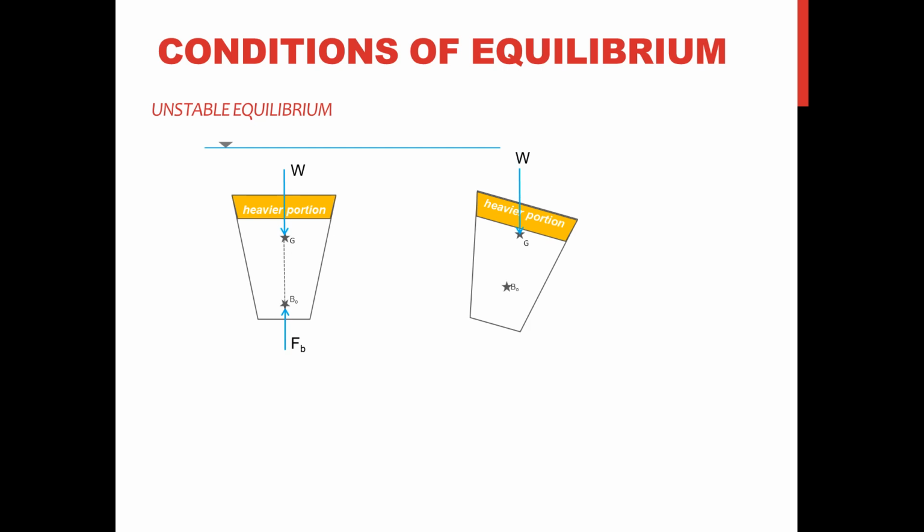Just the same, it will have a center of buoyancy with the buoyant force in it. So again, notice that there will be no collinearity between the weight and the buoyant force. Hence, it will have a distance x. The distance implies a moment or rotation, since W and the buoyant force are in the same direction. This time, it is actually along the direction of the tilting. The direction of the tilting is clockwise, hence the overturning moment.